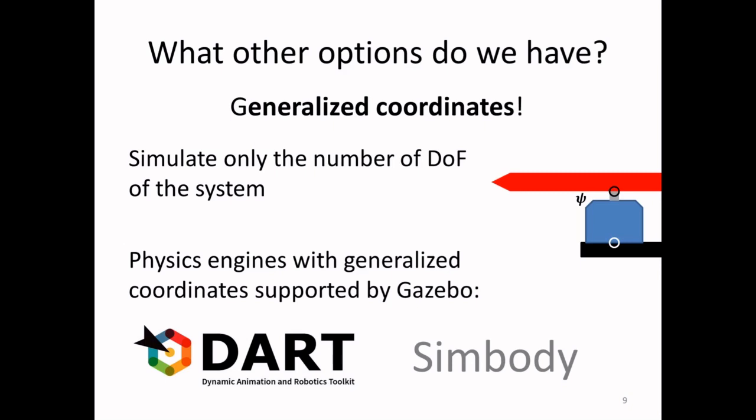We followed the instructions pretty much verbatim on the Gazebo website, building from source on Ubuntu, the latest LTS, and it was very straightforward. We put it on 5 machines and only had one hiccup because the DART repositories were changing so drastically. But if you install DART from source as well, using version 6.7, I haven't had an issue yet, and it's pretty smooth to install.